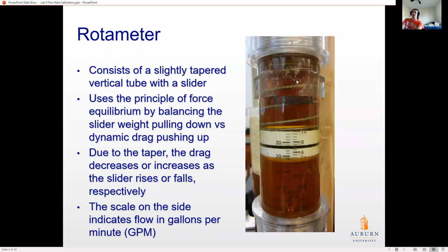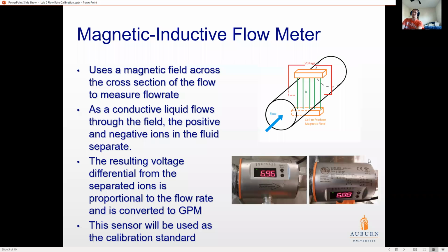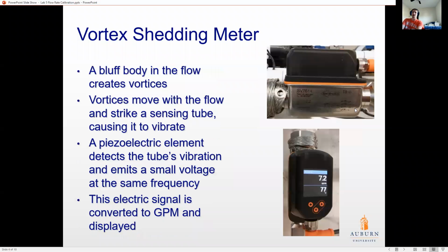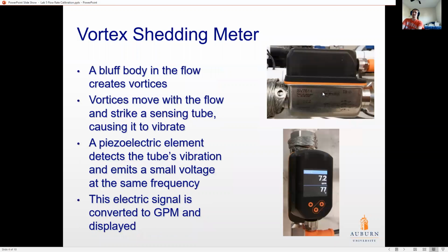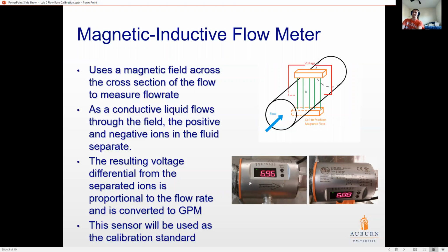And we're going to try to force the other two sensors, we're going to calibrate them so that they read the same thing that this one did. That's the idea of how you do direct calibration. So we're going to say this thing had the correct measurement, and we're going to try to add a correction to these two sensors to make them read the same as this one.